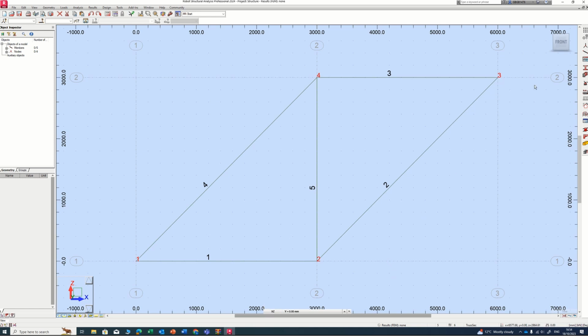So after that, what we need to do is apply the support to these structures. So I'm going to apply the fixed support. So we then select this fix in here. Make sure you select the fix in here. Okay, this is highlighted. And then you move the cursor, and you can see this cursor is changed to a fixed symbol. So you click on number 1 in there, and you can see this fixed point has been allocated, and the second point in here will be supported already.